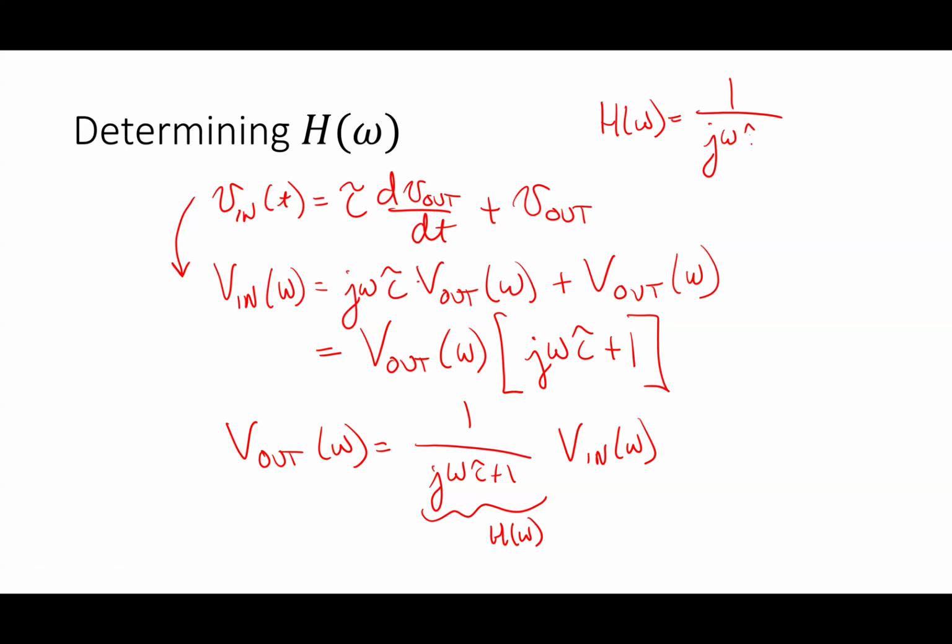Now, what I said last time is if I take the magnitude of this whole thing, the magnitude of that is only going to be zero if omega goes to infinity, right? If omega goes to infinity, then I'm basically going to have 1 over a large number, which is going to be 0. This is never going to be fully equal to 0. And for any real system, you never have these filters have a 0 value, right?